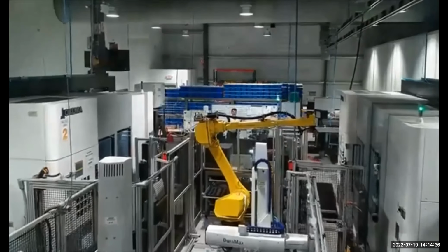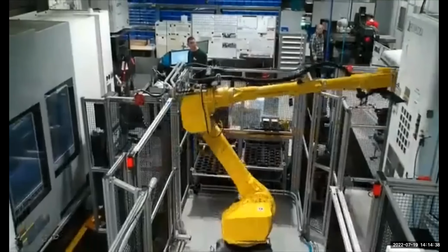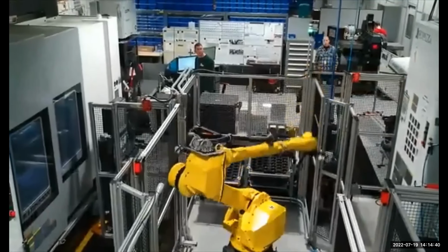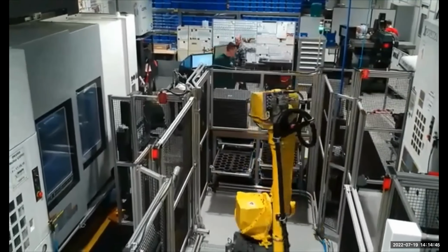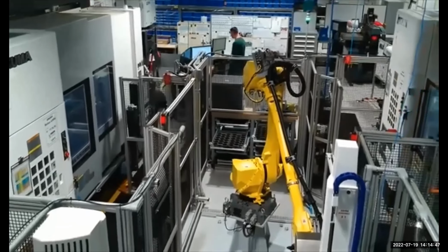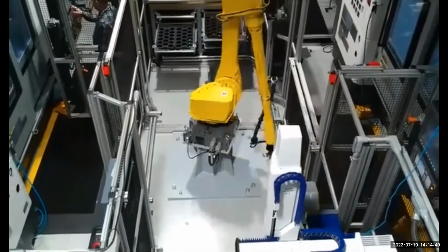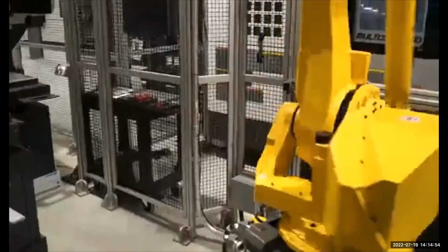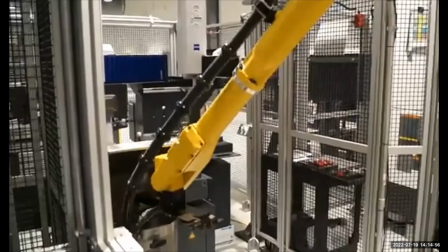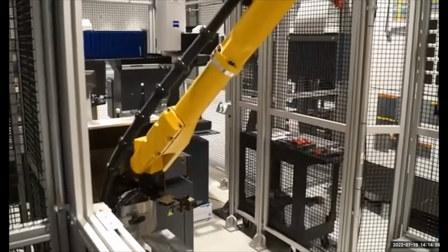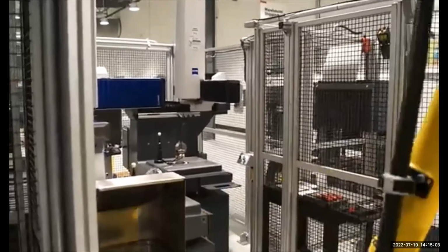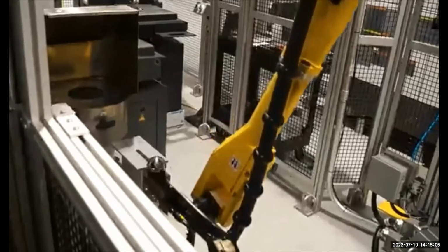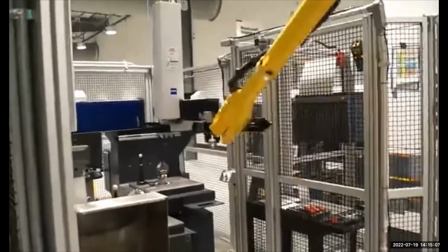As previously stated, the robot handles all interactions within the cell and is the centerpiece of its operation. Each Multis machine manufactures a part following a computer numerically controlled, or CNC, program. The robot unloads a completed part when the machine sends a request, and the manufactured part size is passed via binary signals to the robot when this happens. The robot restarts the machining process on the machine when unload is complete, immerses the part in a jet of air to blow off the cutting fluid, repositions its grip on the part, and moves it onto the CMM fixture.